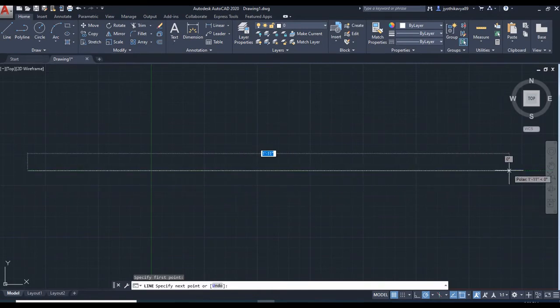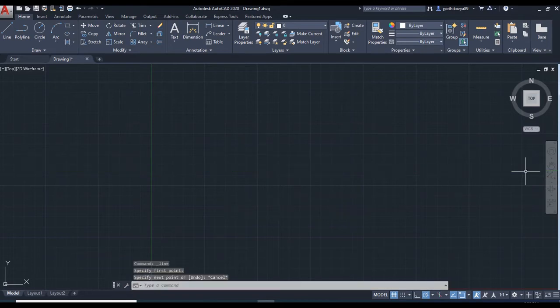We are still not able to draw it. You can see the dimensions there. We are able to draw only 1 feet or 2 feet, right? It is far too lesser if we are trying to draw a 30 feet comma 40 feet plan. It's still not solved. So to solve this, we have to just type zoom command.